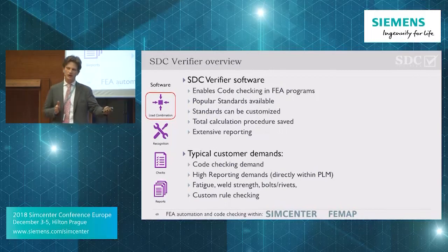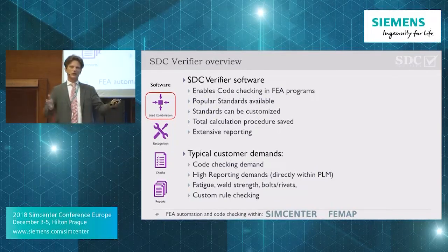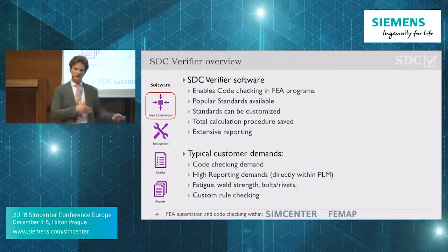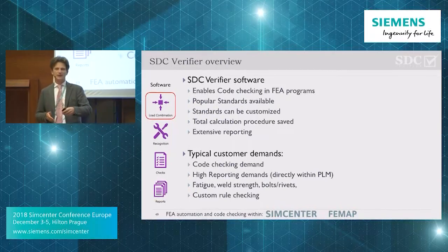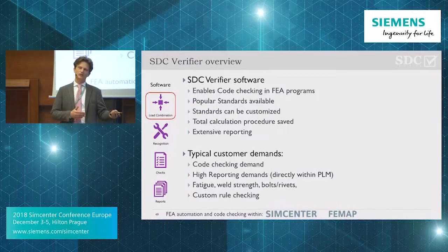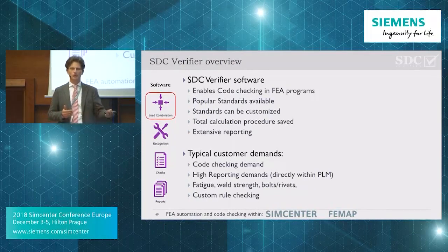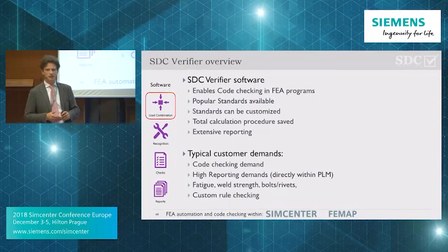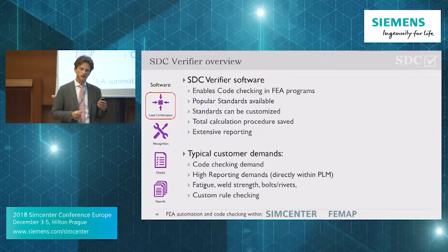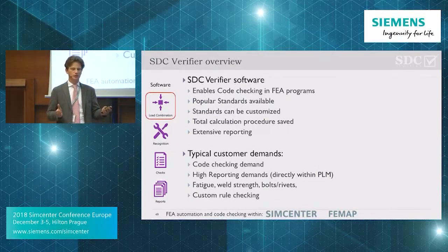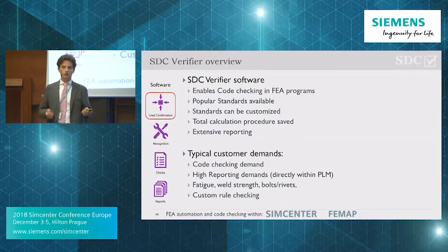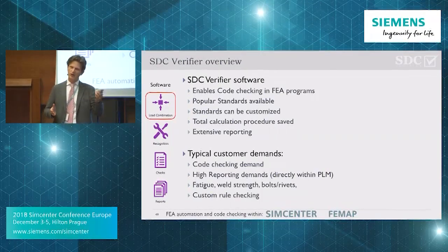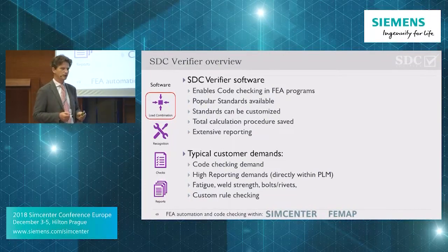So instead of going, okay, let's first get yield okay, then buckling okay, then fatigue okay, then weld strength okay, where each time you have to update your model and only after that can you do the second check, now you do all the checks all at once because you don't lose time in rebuilding your report. So you get a better overview of all your problems. That's one thing. And so you can do with fewer updates because you have better insight. And the updates go much faster because everything is already set up. You update the stuff and all the calculations rerun automatically.